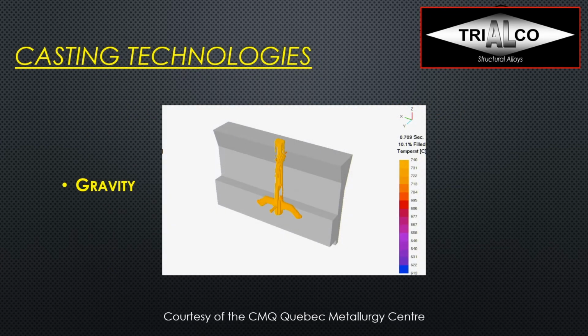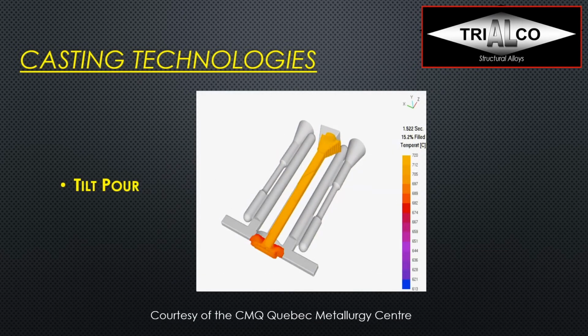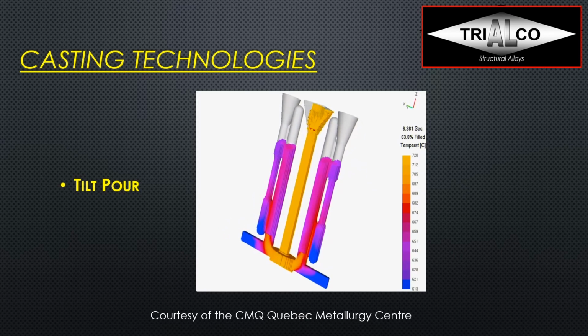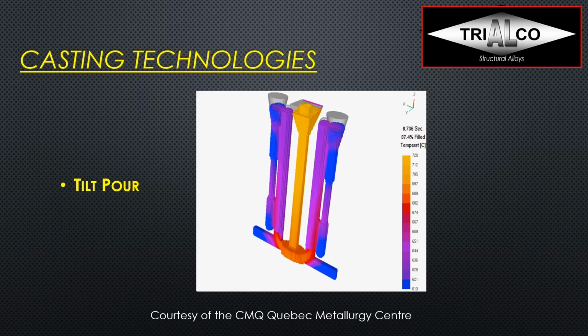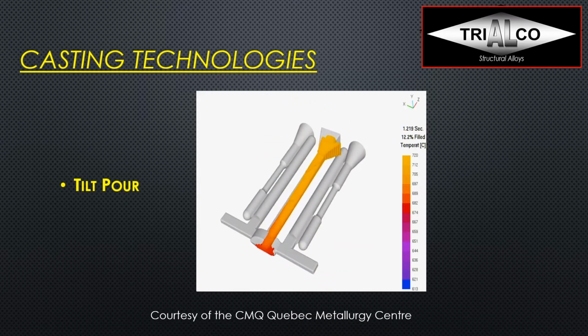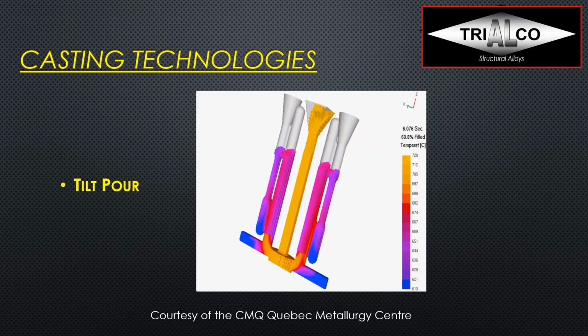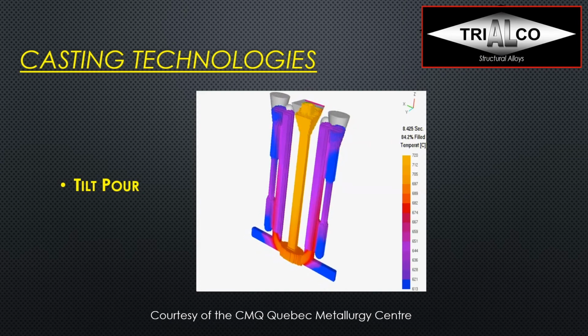So if we look at gravity permanent mold casting or gravity sand casting, either way, we pour the metal in, as we can see in this animation. And typically we don't want to pour directly into the casting itself, but we have a gating system that allows us to smoothly fill the mold cavity. And if we now look at tilt pour casting, well, there it is actually even more visible that we want to smoothly fill the casting itself. So we pour it in and we slowly tilt the mold, and with this we then get a very homogeneous filling of the cavity in a very smooth way.